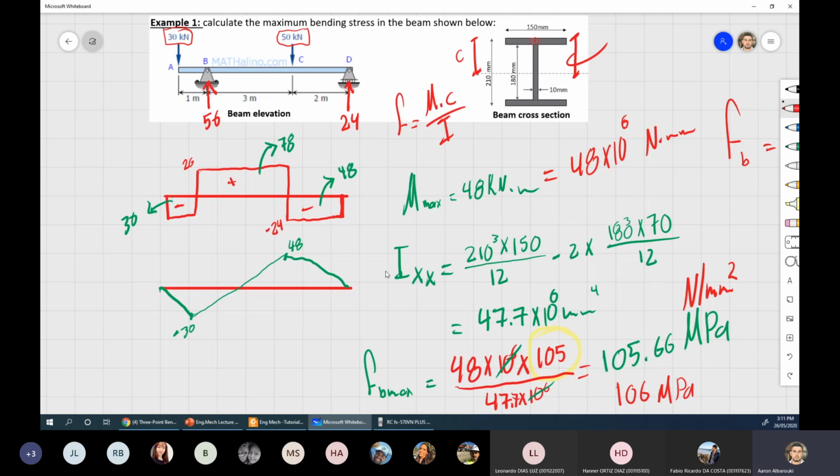So usually steel, because steel is very strong in tension, we don't need to use thick steel. Look at those plates, we always tend to use thin plates, but spaced away from each other. That creates the issue that steel will usually fail more in the compression zone. So when we design, that's what we'll be learning in more detail next semester. When I design a steel beam, I'll always be concerned about what we call the critical flange.